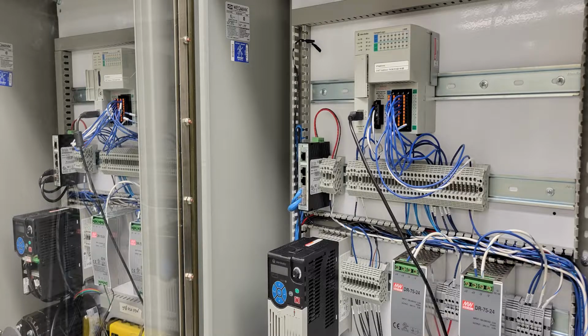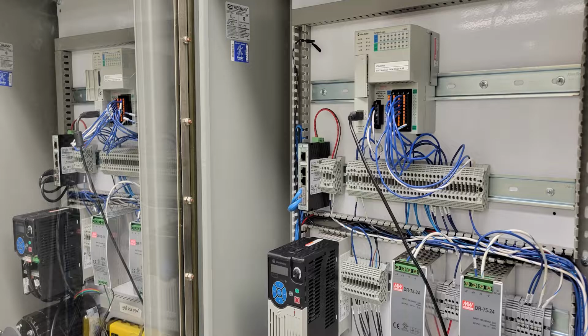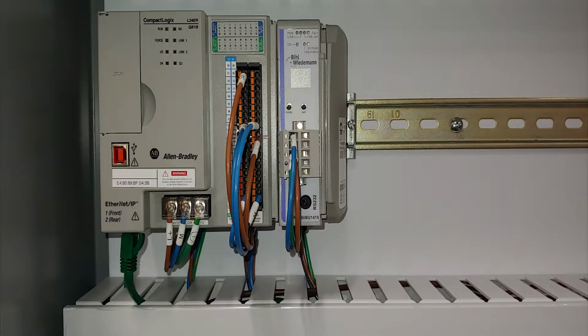In order to monitor or edit PLC code, you need a PLC with power applied, you need a computer that has the programming software installed, and you need a communication setup, and that includes hardware and cabling as well as drivers configured to allow your computer to talk to your PLC. So let's start with the PLC.